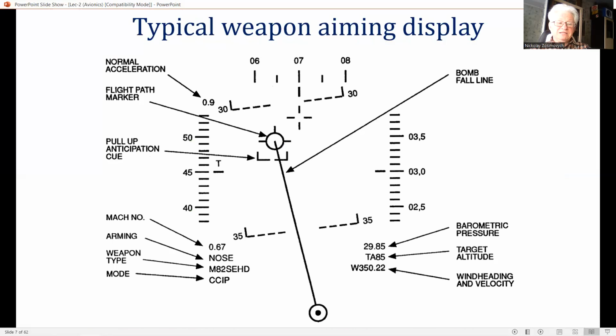The pilot is thus free to concentrate on the outside during maneuvers and does not need to look down at the cockpit instruments or head-down display. It should be noted that there is a transition time of 1 second or more to refocus the eyes from viewing distant objects to viewing near objects a meter or less away, such as the cockpit instruments and displays, and adapt to the cockpit flight environment.